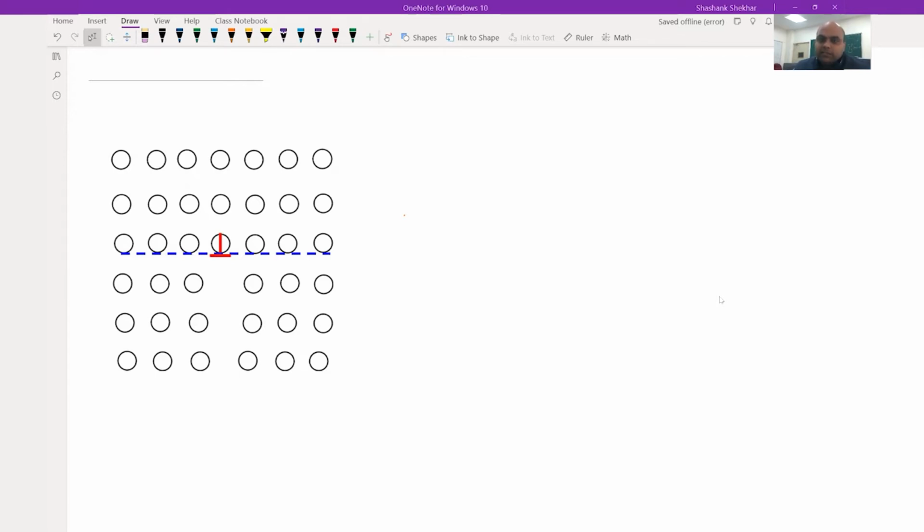In the last lecture, we discussed how substitutional and interstitial atoms interact with edge and screw dislocations. Now let's consider an edge dislocation where these substitutional and interstitial atoms are going to sit. Here I'm showing an edge dislocation. You can clearly see this is your extra half plane. This particular plane is your slip plane.